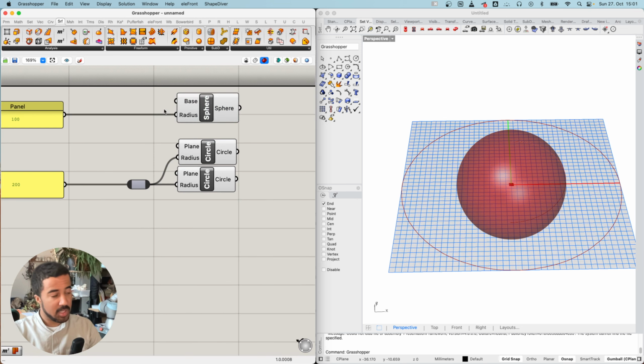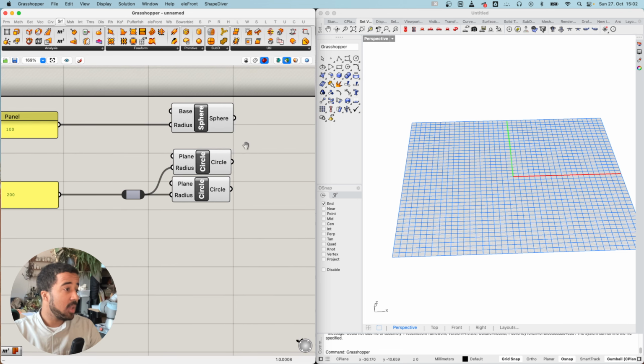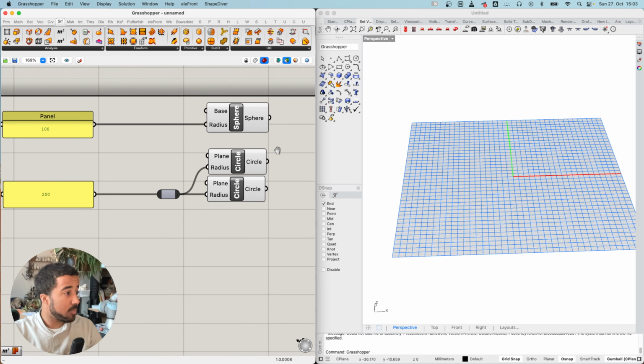This can be very helpful if you have a lot of geometry and you would usually activate all of their previews by right-clicking. However, sometimes you really just need one or two specific geometries, so you can select the option to only draw preview geometry for selected objects, and then you will only see these specific previews.